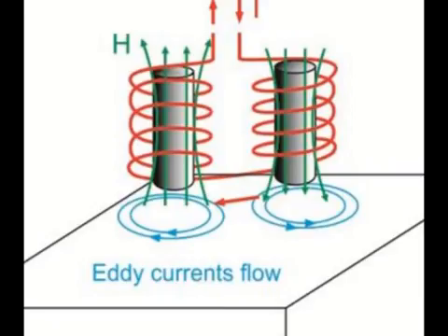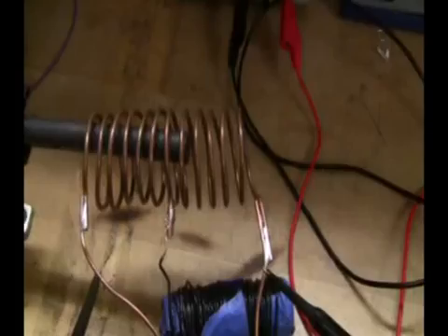When the object that is being heated is inserted inside the heating coil of the resonant tank circuit, an inductive link is formed. The energy in the magnetic field induced by the rapidly changing currents passing through the coil induces very large currents in the object. This is because a solid object can be seen as a single-turn inductor, and the turns ratio of two coils is inversely proportional to the currents through each. These currents are specifically known as eddy currents, and when passed through the conductor, produce heat in what is known as joule heating.